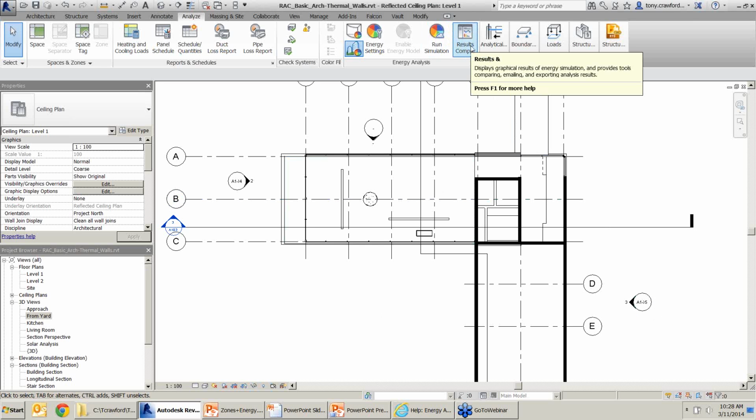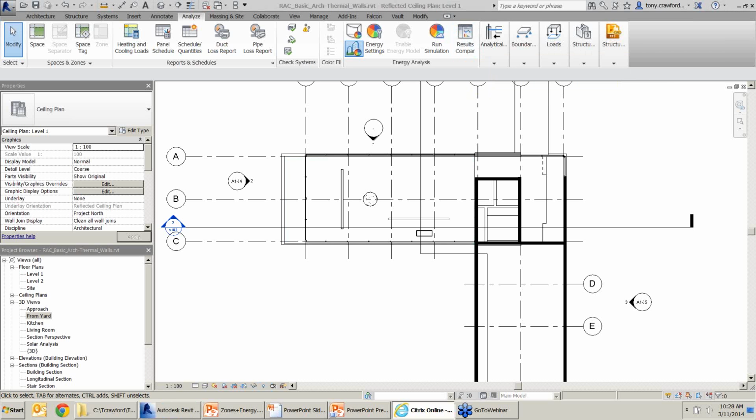One of the things, Tony, you mentioned you needed a live model in these phases, and one of the things that's nice about that is, as Tony said, it'll take the actual thermal properties of CMU or wood floors versus stone floors, things like that, and allow you to use them. So you can set up models with design variables and say, okay, if we put in CMU versus some other wall type, what's it going to do, and run several types of analysis at once.